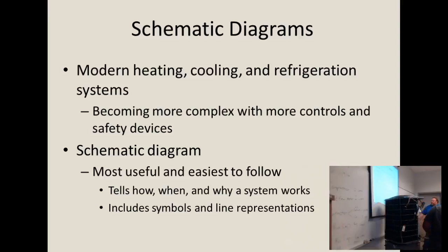All right, so I got 3 wires from the fan motor, 3 wires from the compressor. Let's start off with step 1. We say we have 240 coming in, 24 to the side, and 240 coming out. So we're going to say this top side is the line voltage coming in from the disconnect, and this bottom side is the 240 going to the load.